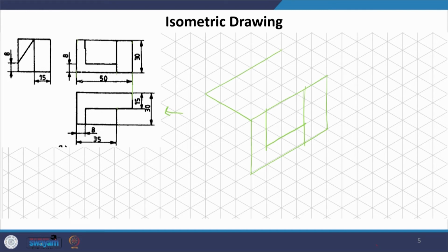So, what we have here is, we have say approximately this much here and we have this here, there is nothing here. Okay. Now, when we are converting ortho to iso, we know that there cannot be any hanging edge, it has to converge, it has to merge. So, we automatically know that this face has to go back, but we will do it later. We will first draw the side elevation.